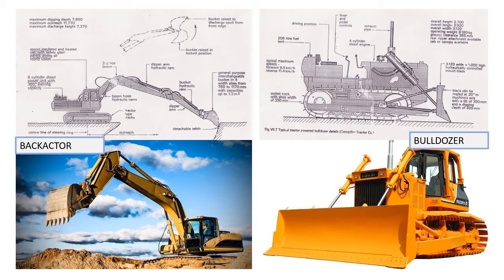The main function of bulldozer is actually for shallow excavation up to 300 mm deep, either on the level of ground or side hill cutting. Other than cutting purpose, it can be used for clearance of shrubs and small trees. Clearance of trees by using a raised small blade as a pusher arm. It can also be used as towing tractor and can be acting as a pusher to scraper machines.